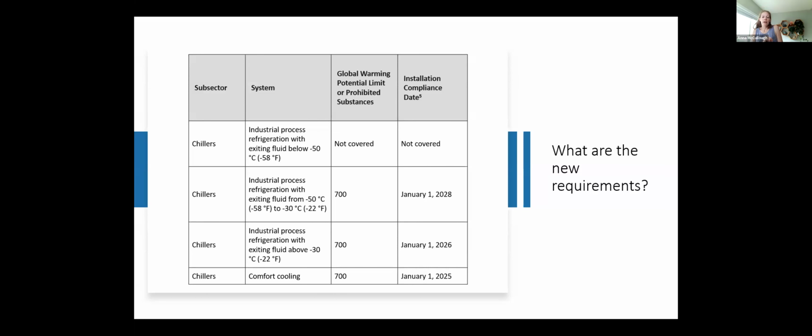Yeah, absolutely. So there are a couple different considerations once you leave your protected shaft. The first is if you have a safety shutoff valve when you leave the shaft. I think about chilled water, heating hot water, when you have safety shutoff valves at every riser, right? You are reducing the amount of refrigerant that can be leaked from the shaft into that return plenum, from both sides of that safety shutoff valve.